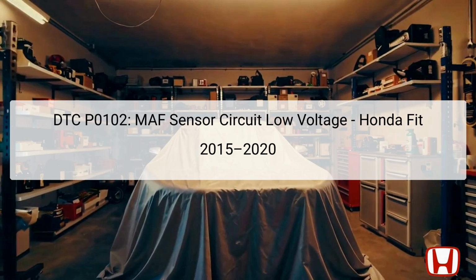Accurate functioning of this sensor is crucial, as the engine control unit, ECU, relies on its readings to adjust the air-fuel mixture for efficient combustion. A malfunctioning MAF sensor can lead to decreased engine performance, increased emissions, or even engine stalling, making it important for vehicle maintenance.